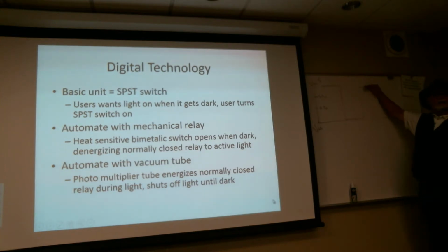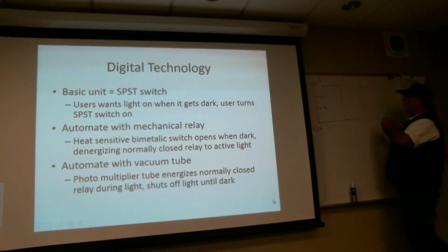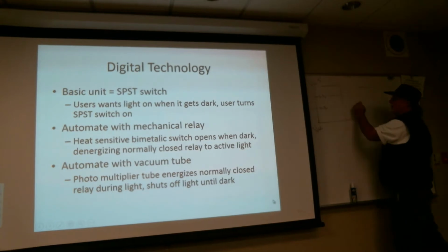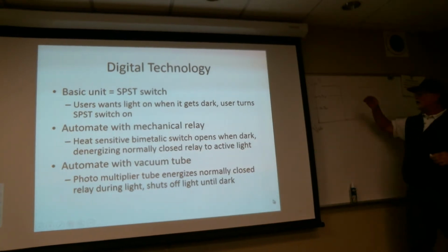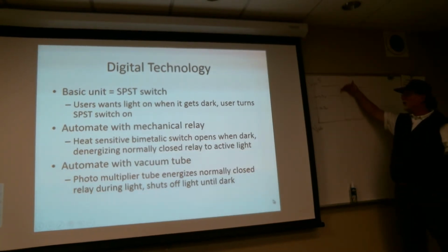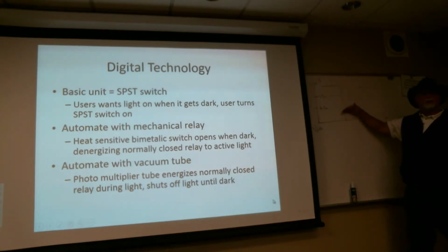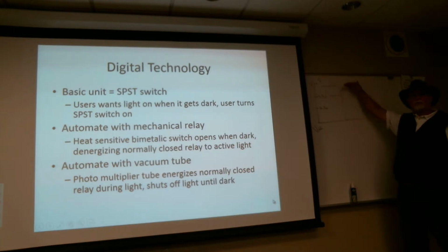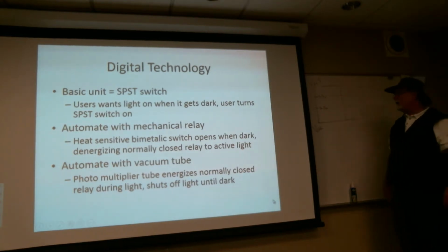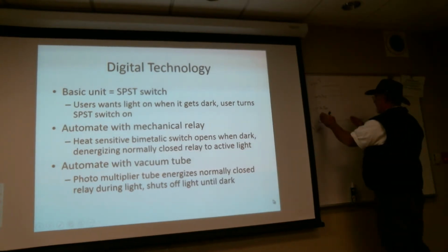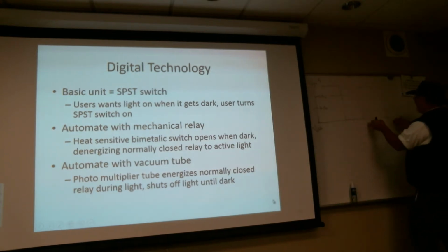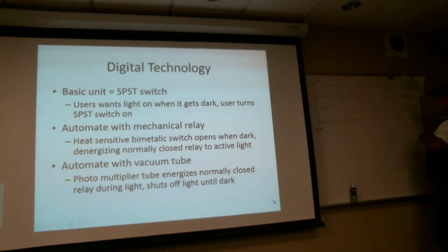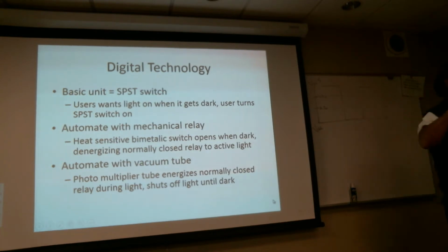Or we could do it the other way and say there's a quasi no man's land in here, which says as long as it goes from something above 3.3 and passes to something below 2.3, we're going to say it's a transition. But if it just dips down to here and then goes back up, it wasn't a transition. Okay, so it stayed high the whole time. Now data is going to be, we're going to say data bit 1, data bit 2, data bit 3, data bit 4, data bit 5, high, low, 0.